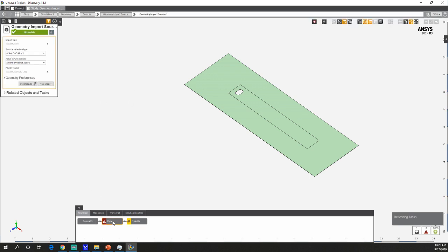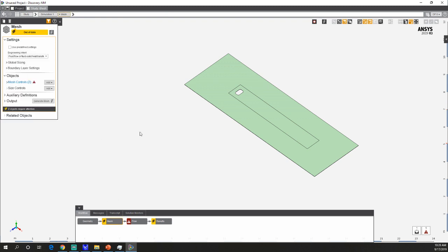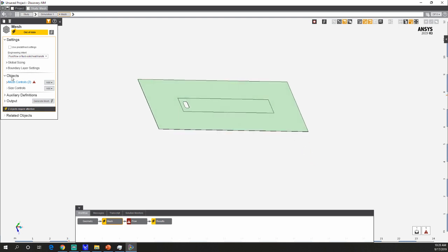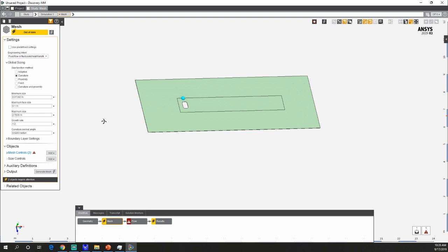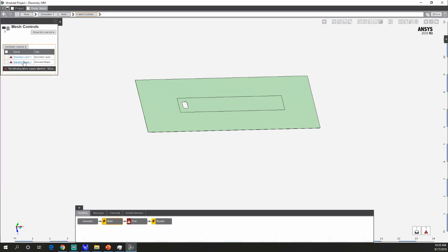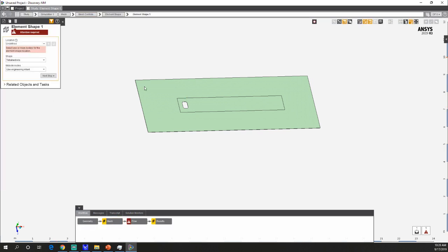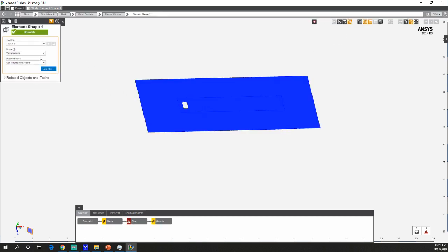I think I definitely want to define the mesh manually. Okay, so a quick recap of all the things we did. We adjusted the global size setting. Wow, 1 meter, that's really huge. So let's do 110 centimeters. On the mesh control size, elements, we want this to be automatic, or actually hexahedron.